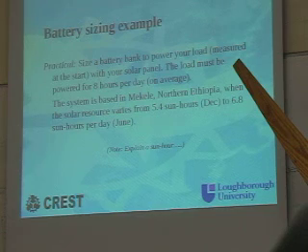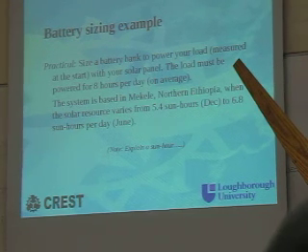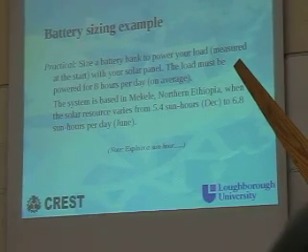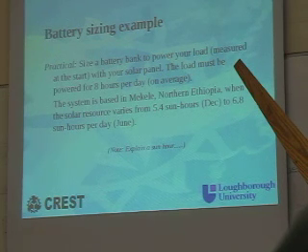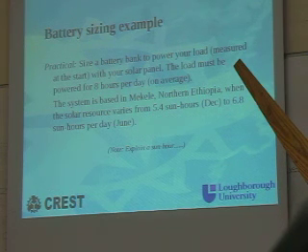We could do this practical. You've got your load, the loads that we were talking about before, and you've got your solar panels on your tables. What I want you to do is design a battery bank to power the load that you have on your table with the solar panel that you have on your table. The load is going to be run for 8 hours a day, and it's based in a place in Ethiopia. That's where my brother is at the moment, that's why I've chosen it. And the solar resource varies from 5.4 sun hours to 6.8 sun hours per day.